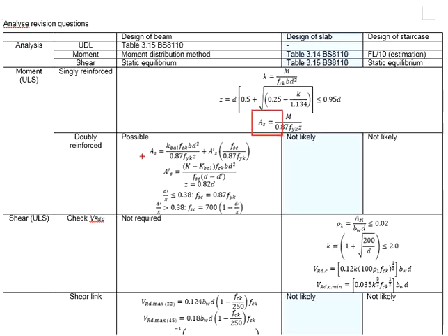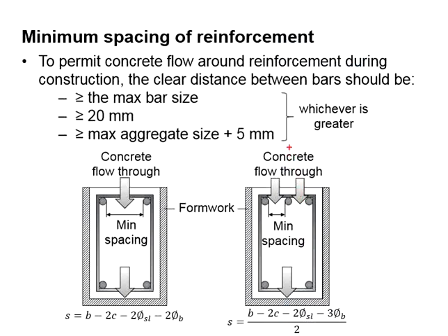Based on the amount of reinforcement bar calculated, you will need to propose a suitable number of reinforcement bars and a suitable size. And then you have to arrange the reinforcement bars in a manner that is symmetrical at the center. This is the arrangement of a typical 2 reinforcement bars for the beam. When you have 3 reinforcement bars, they will be arranged in this manner. 4 reinforcement bars, they will be arranged in this manner, and so on and so forth.